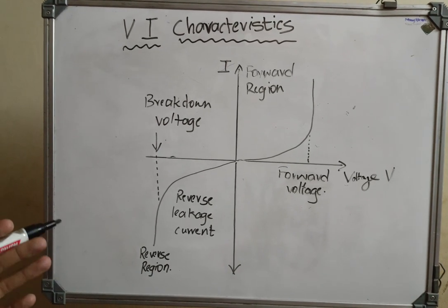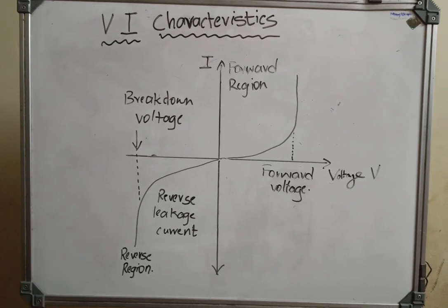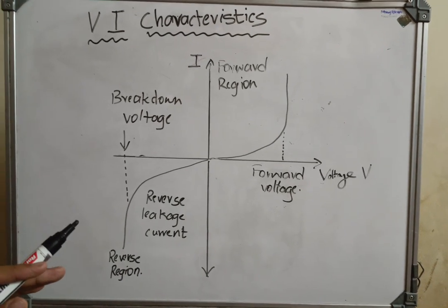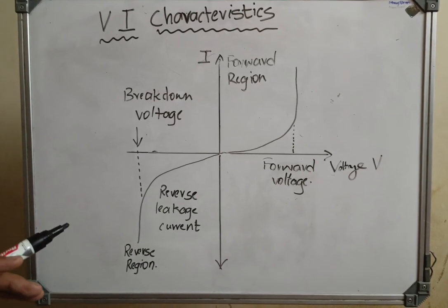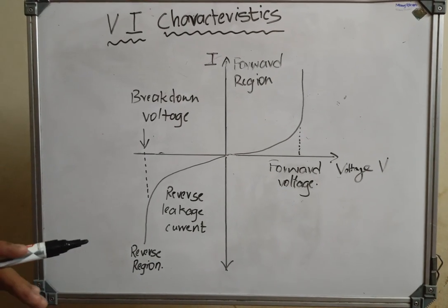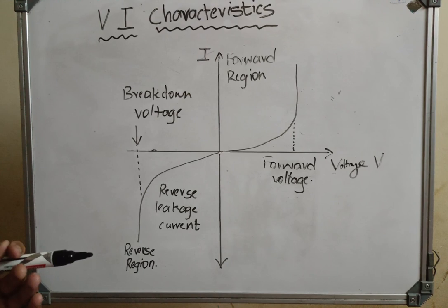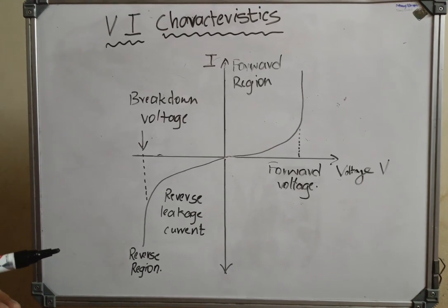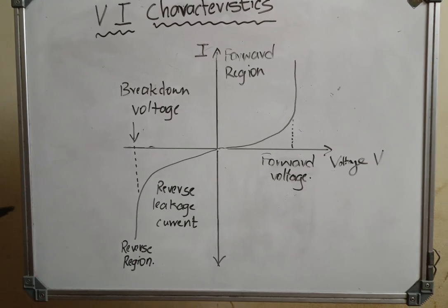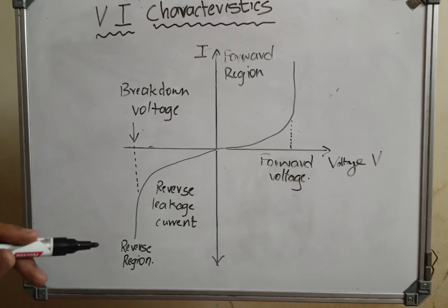When the diode is in forward bias, the current increases slowly, and the curve obtained is non-linear as the voltage applied to the diode overcomes the potential barrier. Once the diode overcomes the potential barrier, the diode behaves normally and the curve rises sharply as the external voltage increases, and the curve obtained is linear.